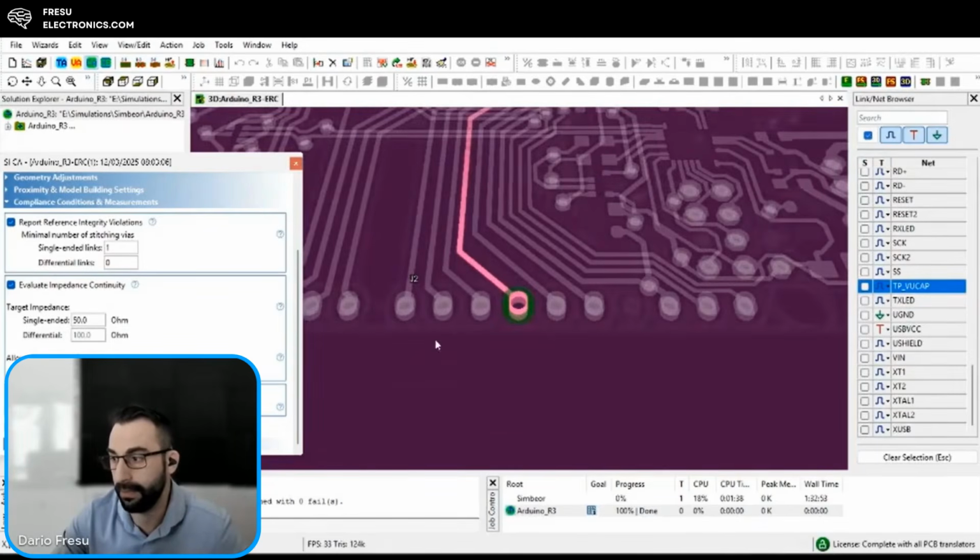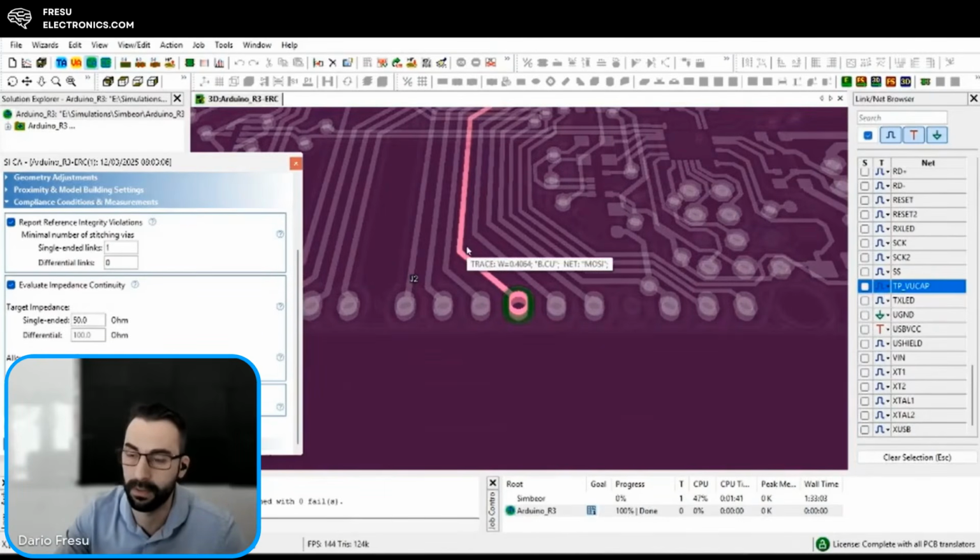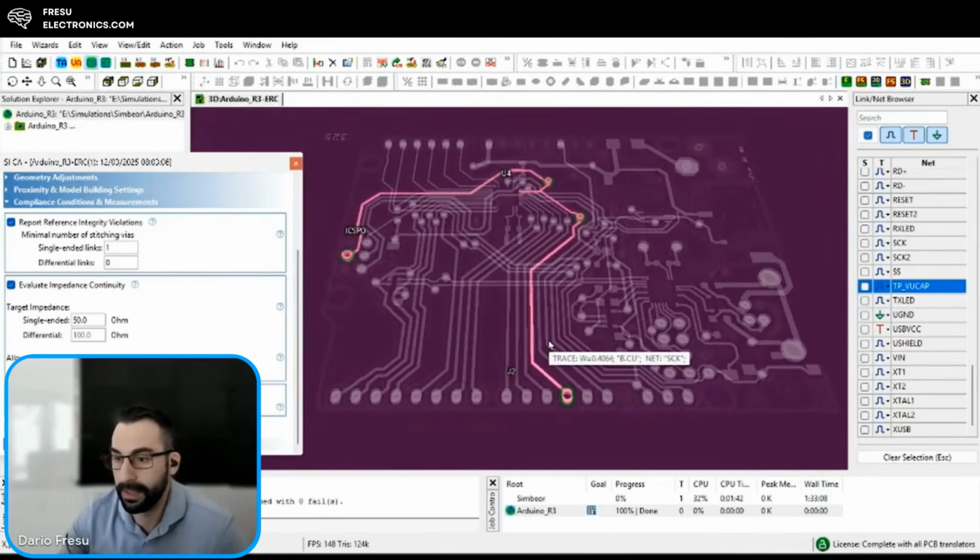Because if I have a filter placed in the input and output connectors, then I have more chances to stop the signal from propagating outside of the board, even if I have internal cross-coupling. So you see, it's all about fundamentals. We didn't show equations now. We talk about three different things: the return and reference plane, the impedance discontinuity, and crosstalk.